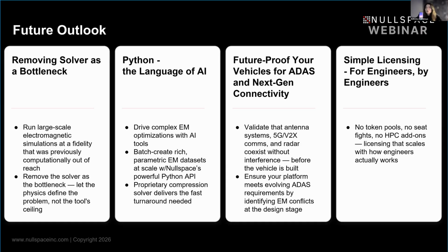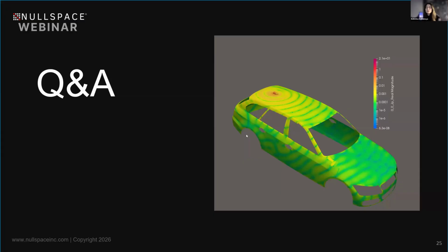What I would do, if I really needed to design this antenna, is go back to single antenna simulation, and keeping in mind what I had with my glass roof simulation, I would adjust the antenna, maybe make it broader in bandwidth, especially on a lower frequency. Then I would have this tolerance to cover the frequency shift when I have different configurations. And that's how I would do it.